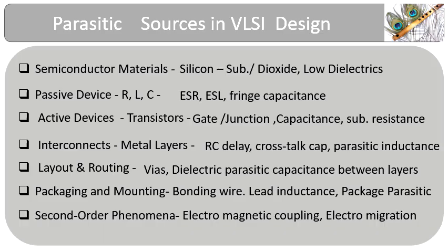Physical placement and routing determine the chip density, but closely packed wires increase parasitic coupling and delay. Chip packaging and assembly provide electrical connection and cooling but add to parasitic resistance, inductance, and thermal stress. At nanoscale, second-order effects like process variation, temperature rise, and substrate noise reduce yield and reliability. A holistic approach, from materials to packaging, is essential for high-performance and robust VLSI designs.